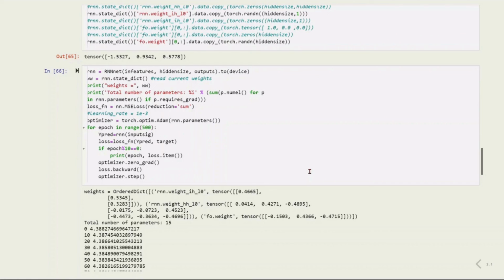We use mean squared error loss, and also we use an optimizer, which is the ADAM optimizer with default values. So what we want now is that our network learns this behavior, how to behave exactly like the infinite impulse response filter that we calculated before, by giving this target and running a complete experiment, and we will have then the output of our network. We will compare and we will see if it learned properly.